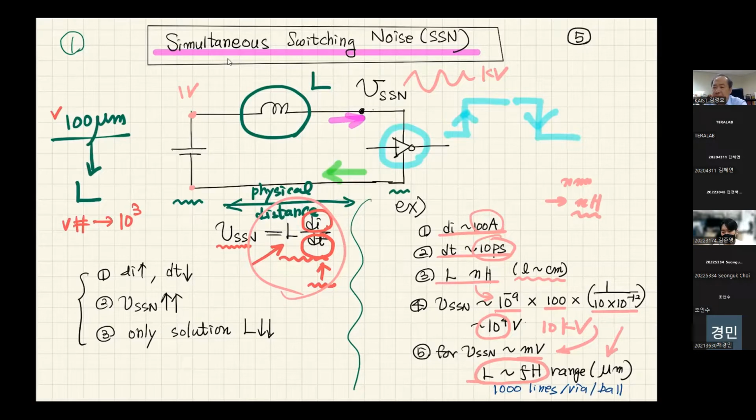That is why I keep saying that a semiconductor system has to be three-dimensional, so that you can put the battery underneath your chip, and your circuit is just over the wafer. Then if you thin down the wafer thickness, you're going to minimize the inductance, and you can increase the number of power interconnections.